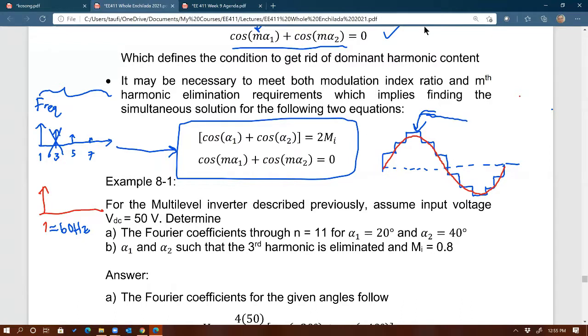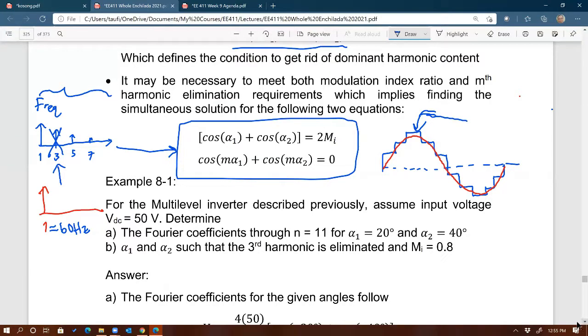But imagine if the third harmonic is still there. You're going to have to use big inductors, big capacitors, to get the right cutoff frequencies. But if number 3 is eliminated, then the next harmonic will be number 5, right? That's further away from 60 hertz, so it'll be easier for us to filter. Okay. That makes sense. Okay, good.